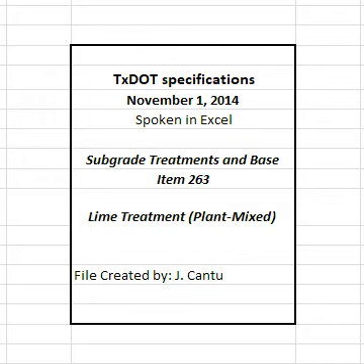4.6 Curing. Cure for at least 7 days, unless otherwise approved, by sprinkling in accordance with Item 204, sprinkling, or by applying an asphalt material at a rate of 0.05 to 0.20 gallons per square yard as directed. Maintain moisture during curing. Continue curing until placing another course or opening to traffic. Open to traffic as directed. Do not allow equipment on the finished course during curing except as required for sprinkling, unless otherwise approved. Apply seals or additional courses within 14 days of final compaction.